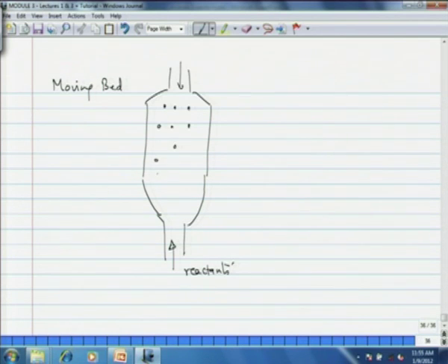However, unlike fluidized bed reactors, here the velocity of the reactants is sufficiently small that all the flow occurs between the voids and there is no movement of the particles in the direction of the reactant flow. So particles move continuously down slowly, and these are removed at a side outlet.